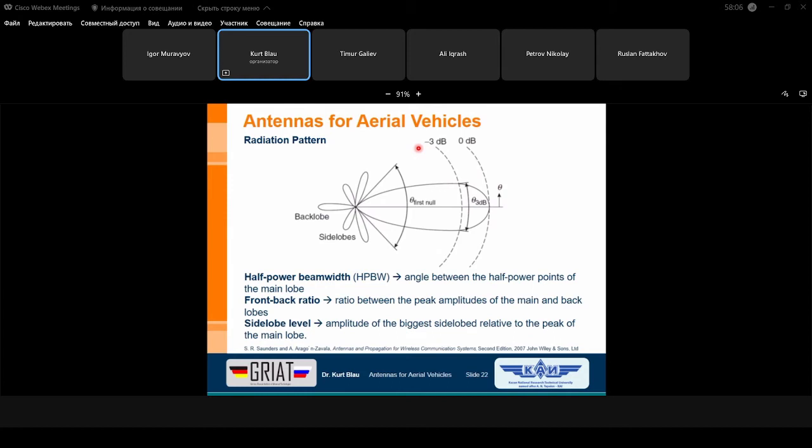What can we do with the measured or determined radiation pattern? This is a question, and you can see here only a more or less primitive example of such an antenna. It's not a dipole, it's clear, it's another antenna. Why is it not a dipole? Because we can see here that our main pattern is much smaller than what we have seen in the slides before.